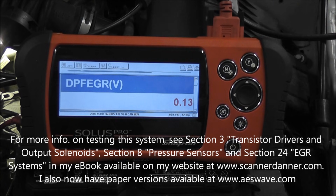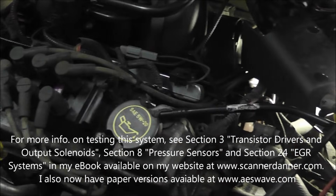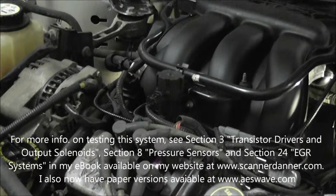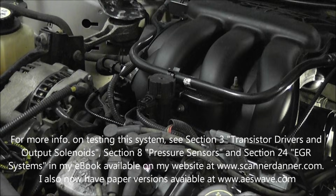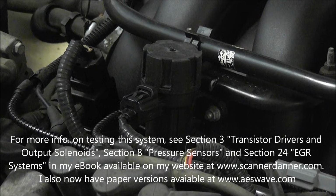So when we do this test, again, we want to hear the RPM get real rough. So what we're going to do, we're going to go to this EGR and our EGR solenoid. Let me get you a shot of that. Very nice and easy to get to. It's right here in the front. That is our EGR solenoid right there.